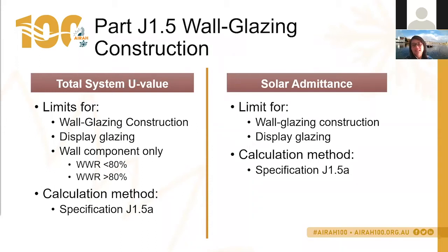Now, in addition to that, we also look specifically at the wall components. When we talk about wall components, we're talking about opaque wall components, where you can't see through that construction. That could be in the form of cladding, concrete, brickwork or masonry, or it could be spandrel panels. In the 2019 code, spandrel panels play a bigger role, and it's now specifically in its own section that gives you guidance on how you deal with it.